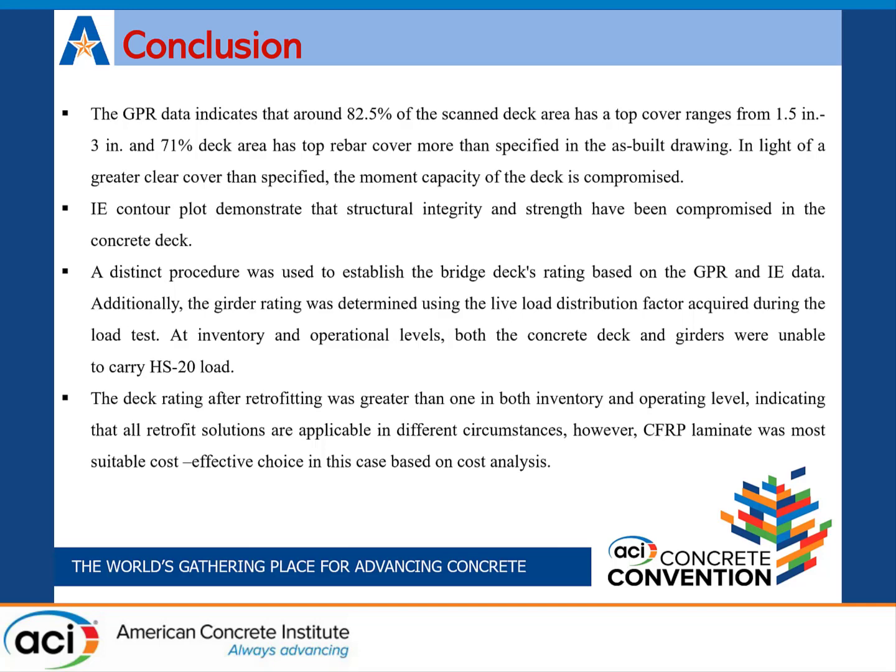Additionally, girder rating was determined using the live load distribution factor acquired during the load testing. Finally, the deck rating after retrofitting was greater than one at both inventory and operating levels, indicating all the retrofitting options are applicable in different circumstances. However, CFRP laminate was the most cost-effective choice in this case based on the cost analysis.